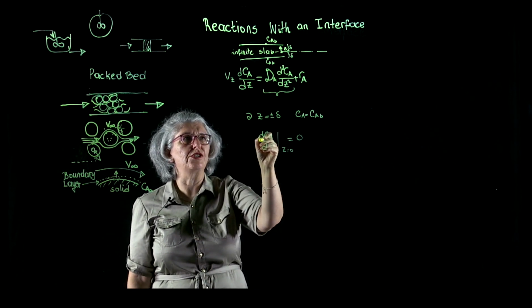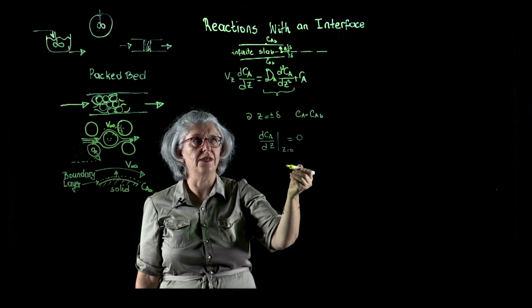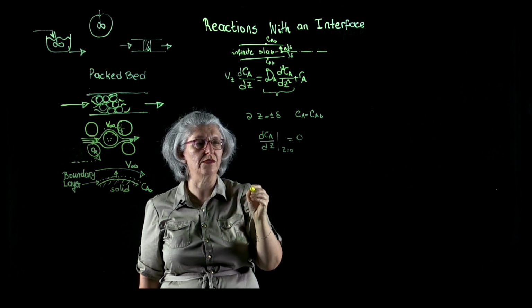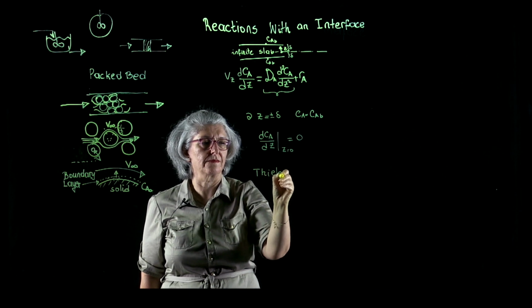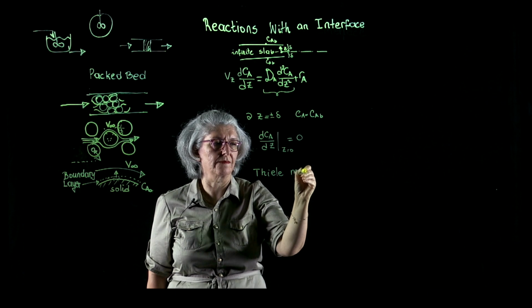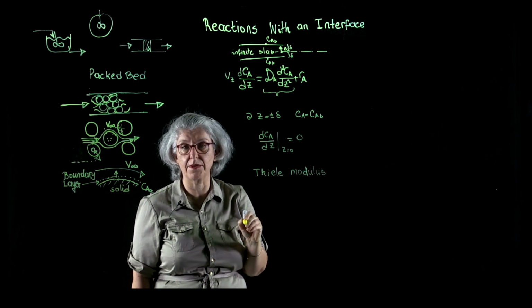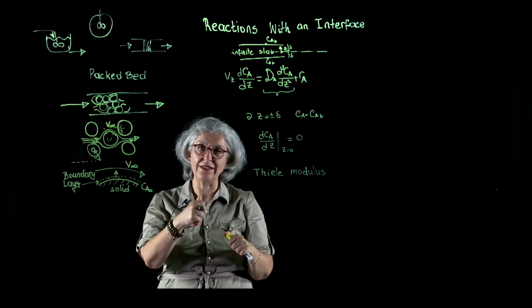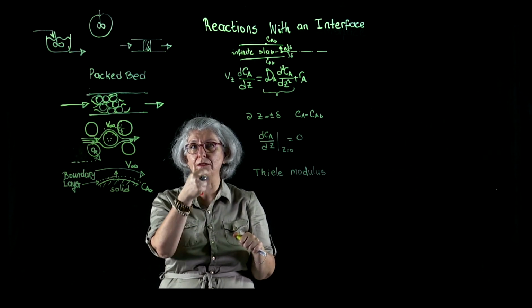Now, the solution of this differential equation is going to bring us a parameter which is called the Thiele modulus, or Thiele parameter. This Thiele modulus is going to scale the rate of reaction with respect to the rate of diffusion.